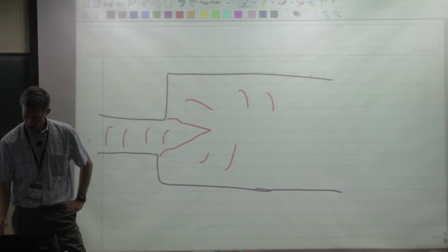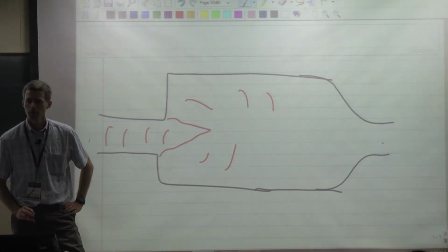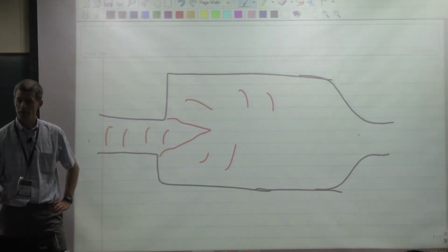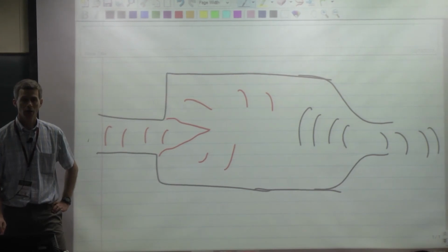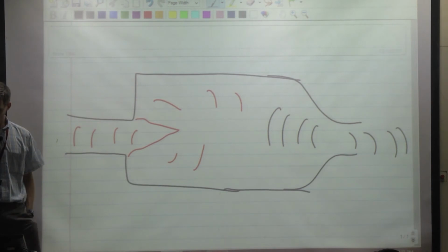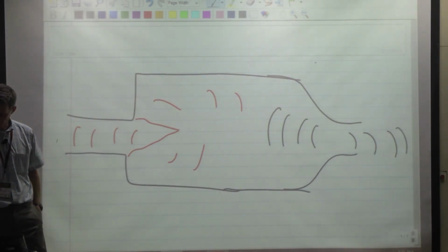However, the situation slightly changes if I accelerate the flow, like add a nozzle. It turns out that if you take an entropy disturbance, just a convecting entropy disturbance, and you accelerate it, that acceleration generates sound. These are sound waves being generated in the nozzle. An entropy disturbance just means that you have a fluctuation in temperature and density. It's an incompressible temperature density fluctuation. But what this means is if you take a straight piece of pipe, that entropy disturbance just convects out of the system. You accelerate that disturbance, you're going to make sound. We call that indirect combustion noise.